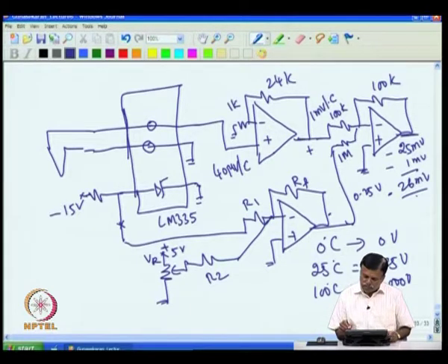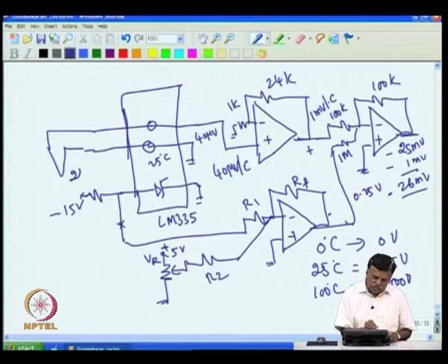So you will get 26 millivolt, representing the temperature as 26 degree, because if this is giving you 40 microvolt here, and if this is 25 degree, then only if this is at 26 degree, then the difference is 1 degree, it would have given 40 microvolt. So that 26 degree junction temperature correctly appears at this output.